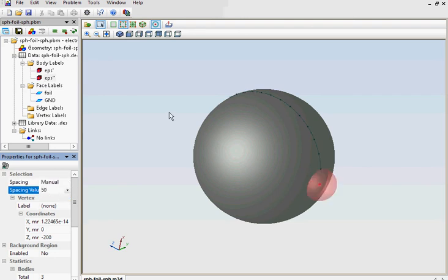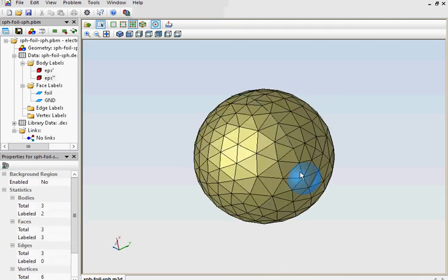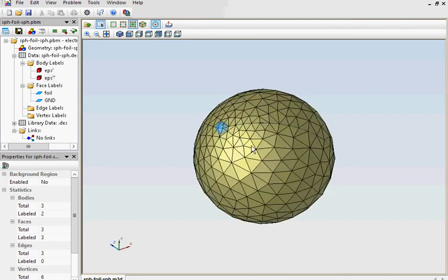You can see that the meshing step is different along this edge. It changes from 20 millimeters here in this vertex to 50 millimeters at this vertex. Surface mesh will follow this pattern. Large triangle elements here, small triangle elements here. The volume mesh will follow this pattern too.